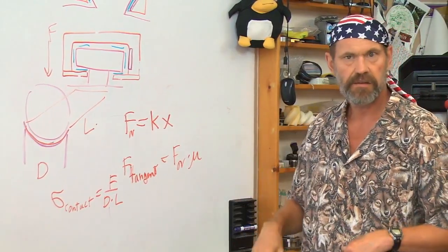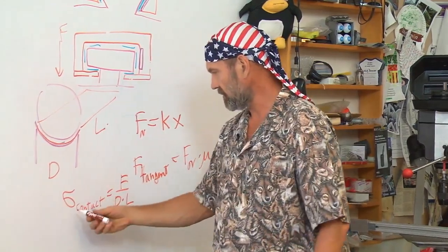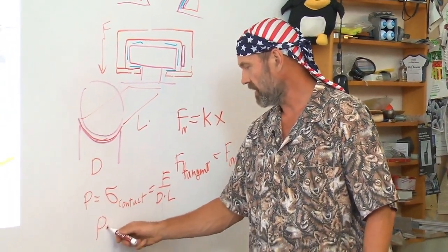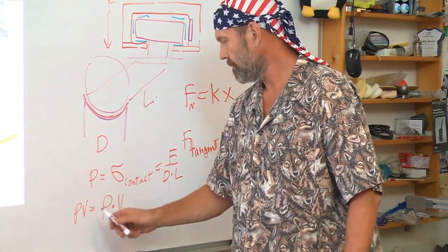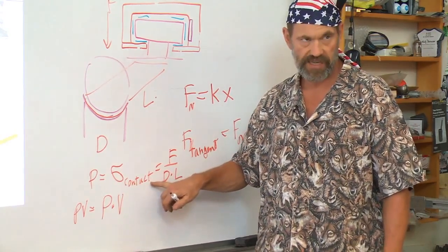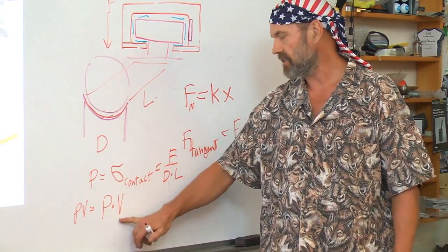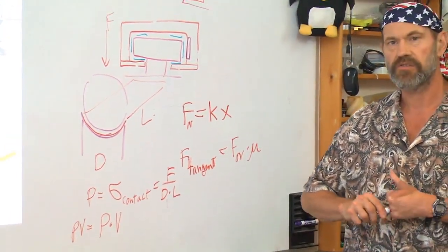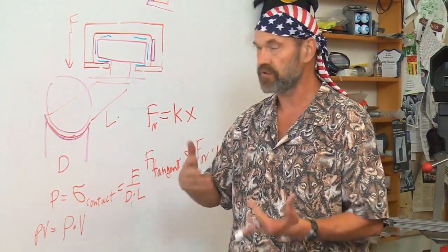Starts hot. Worrying about what is called, this is the sigma or pressure. Sliding contact bearings have a pressure times velocity limit. This is called the PV value. So you'll have to stay below a threshold, or maximum contact stress, and the contact stress you do apply times the velocity you apply will govern the wear of the bearing. That's all covered by the manufacturers in terms of what wear can be expected at different PV values, and what's the maximum PV value before you just burn up the bearing and melt it.